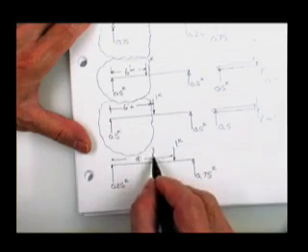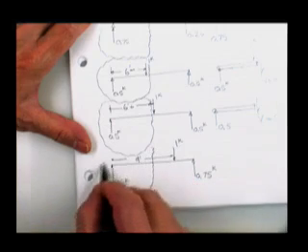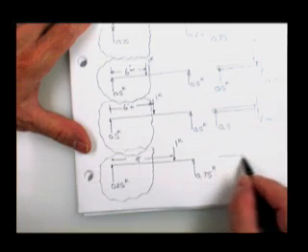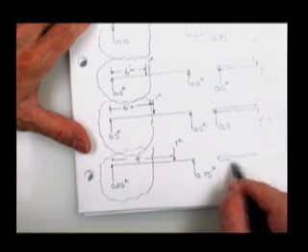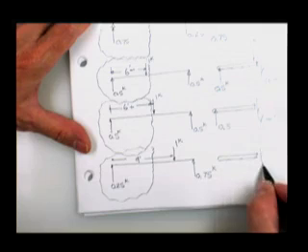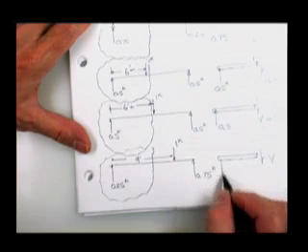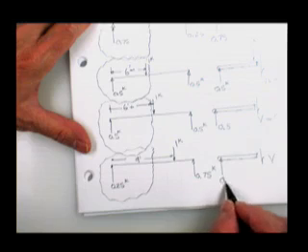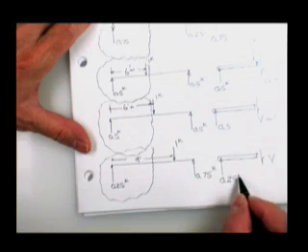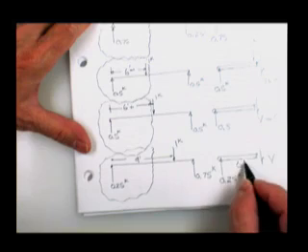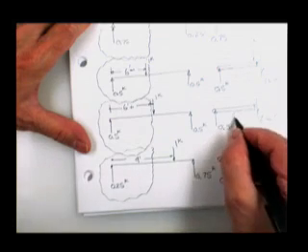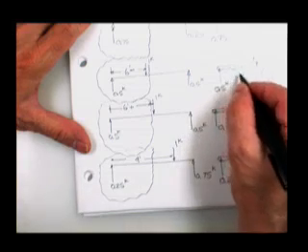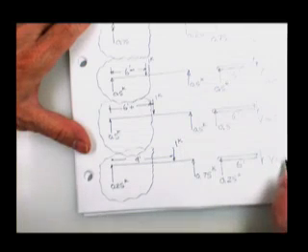Then here's your free body cut at the 6-foot mark. And there's the shear. And here's your reaction, 0.25. And the answer for the shear is 0.25 kips.